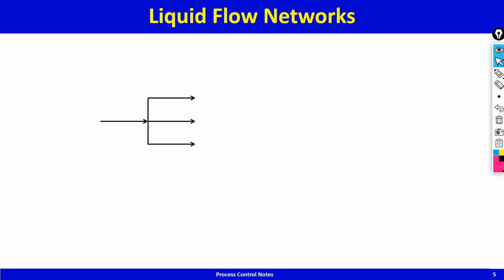Let's look at a liquid flow network. So there's a splitter that splits an incoming stream into 3 output streams. So first question is, how many control valves will we have? Obviously these 3 control valves. And somebody puts a valve here, there's a problem because you cannot independently set 4 valves because of incompressible flow. You'll require that total flow out, F1 plus F2 plus F3, must be equal to Fin, and therefore you're not free to adjust the inflow, and therefore this valve should not be there.